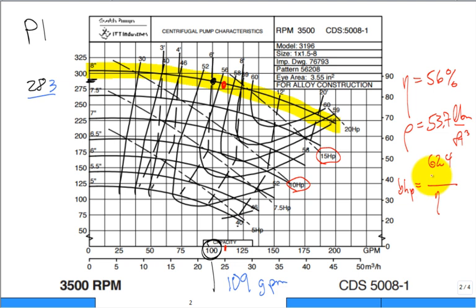That's exactly right. So you have either the capital H head gain, energy head, times the mass flow rate, or you have the pressure gain times the volumetric flow rate, or you have the elevation gain. I'm trying to drill this into you, right? Three ways of writing it. Elevation head gain times, it's kind of the GPM. What is that? Is that a volumetric flow rate?